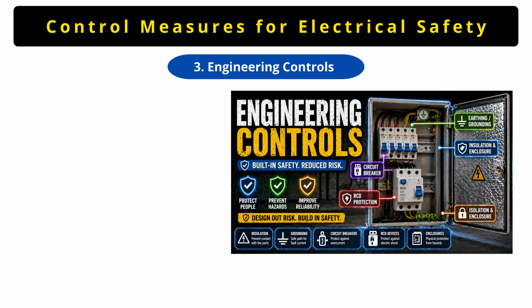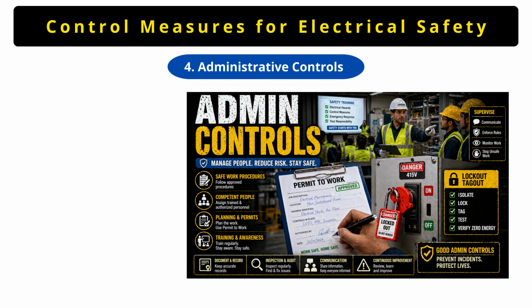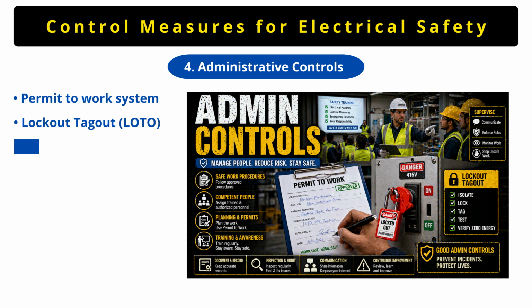Then the third step is engineering controls. You can implement insulation, earthing systems, circuit breakers, and residual current devices, that is RCD, ELCB or RCCB, at your site. Then the fourth step is administrative controls. In administrative control, you can implement a permit to work system, lockout tagout system, training and supervision. So these are the administrative controls you can take.